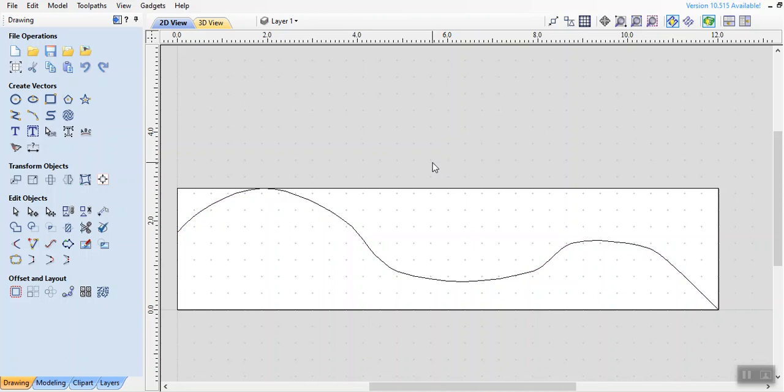Okay. Now I'm going to join this line to the top line. So if you click on this and select the join line command, I just used it before. Click here. I'm sorry, Control Z. I'm taking back. I made a mistake.